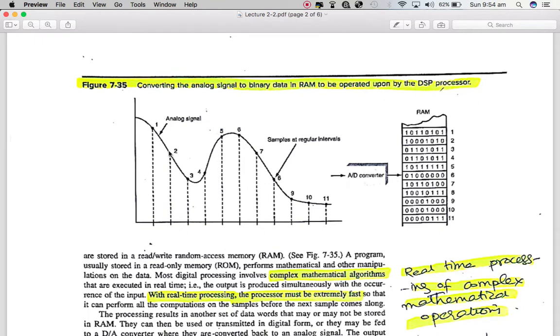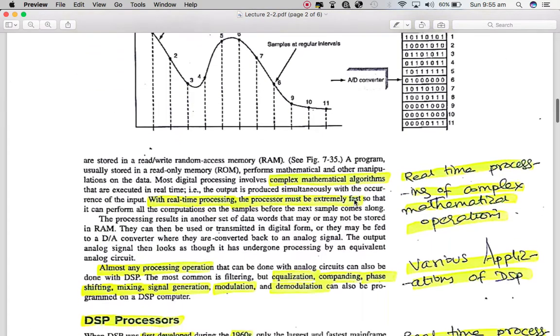And following the shape of the signal and connecting the points of the sampling with the quantized points, we follow the shape of the signal and we have a sampled version of the signal. This sampled version of the signal is then coded with some quantizer, some 4-bit quantizer or 8-bit quantizer. Normally 8-bit quantizers are used, and then every point of the signal is represented by a digital code, and this is how a signal from analog form is converted into digital form.